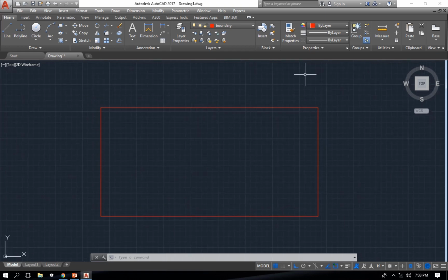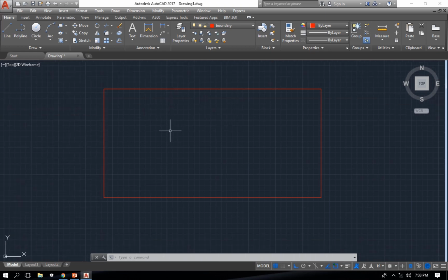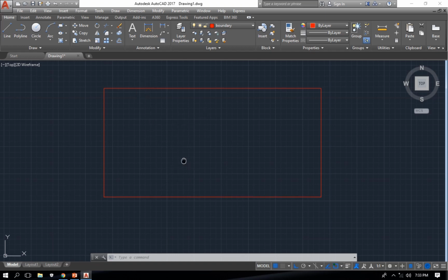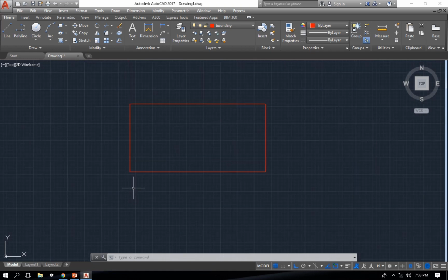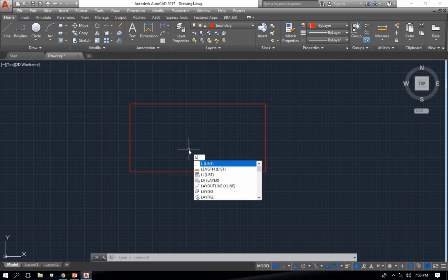So basically for this layout we're going to have plots with dimension 18 by 36 for our plots of land. So every plot that will be inside this layout will be 18 by 36 meters. And mind you, we're working with meters, so everything we do here is in meters. And usually, since it's a hypothetical site, we're going to have a hypothetical existing road. In most cases, most sites in survey plans usually have an existing road, which is expected to provide access into the proposed site. So for this, I would draw a line.